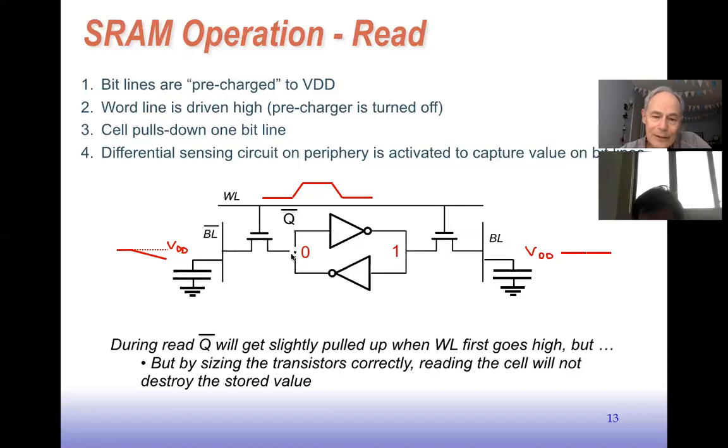So then whichever side of the bit cell is holding a 0, that means the pull down in this inverter is conducting. That will then discharge the bit line down through this cell, right? So effectively, we transfer the 0, and you can see it here. The voltage on the bit line will start dropping down as this cell starts discharging the bit line here. The other side, in this example, is holding a 1, and we can turn on that access device, and there's no voltage across it, so nothing will happen. No current will flow. So that will stay at a high voltage.